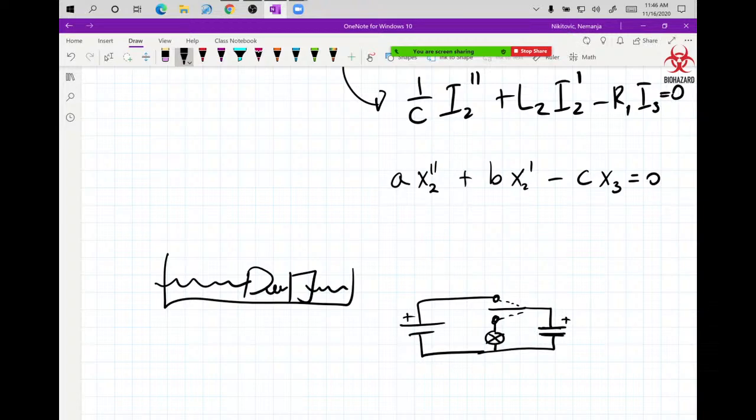Now this is a capacitor, where the two sides are the same. The battery has a longer side for the plus and a shorter side for the minus. When you flip the switch up, it charges the capacitor. Then you switch the switch down, this circuit is active and the other circuit is off, and now the capacitor gives its charge and lights up the bulb.